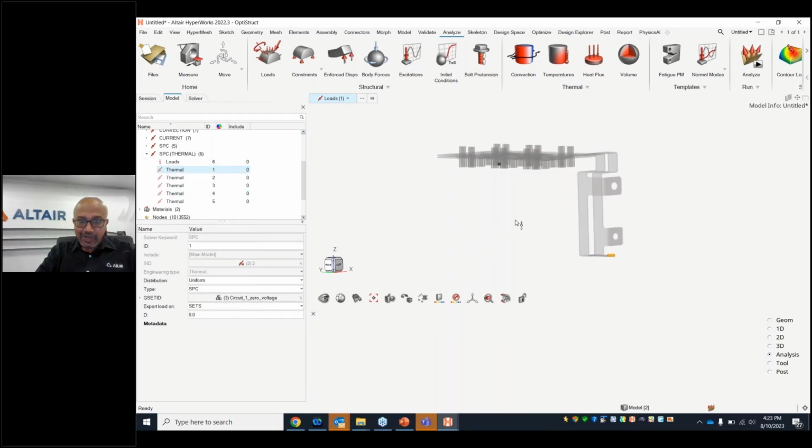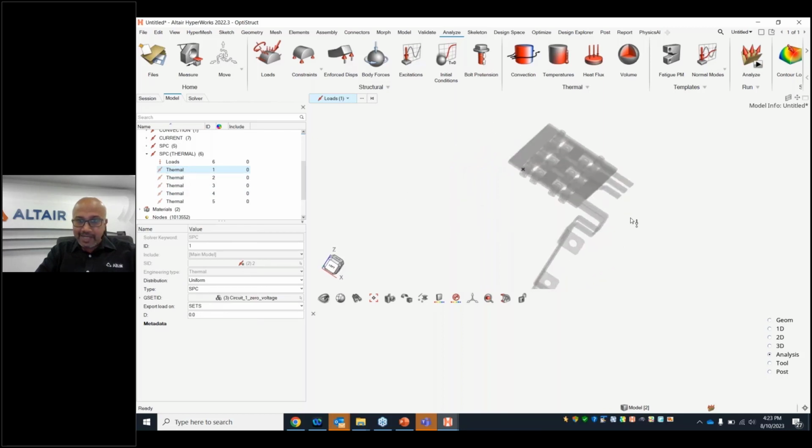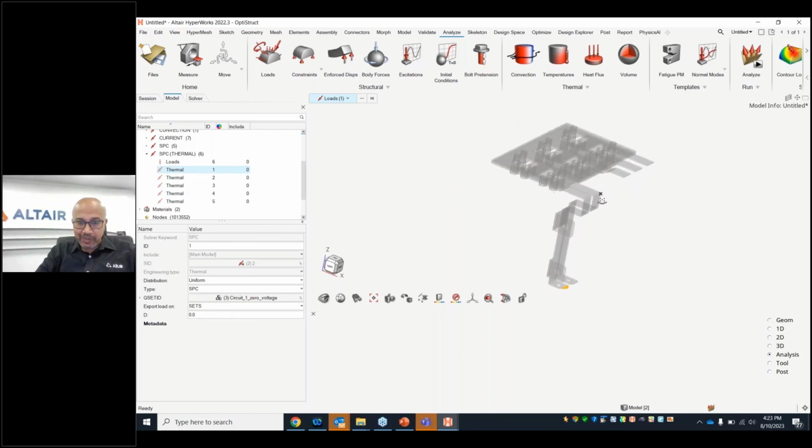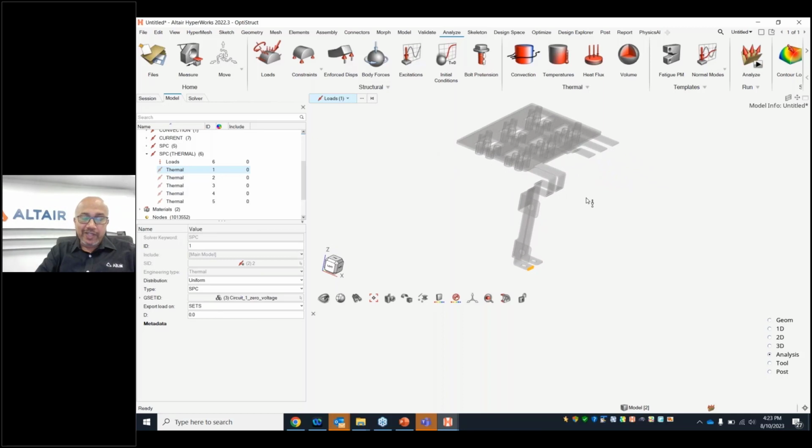Review, yeah. So at various locations, I'm setting the voltage to 0. Because for the current to flow, it will flow from the high potential to the low potential. So in that way, it requires this boundary condition. Either it should have some value, or it is set to 0 as the region from where the current is outflowing.